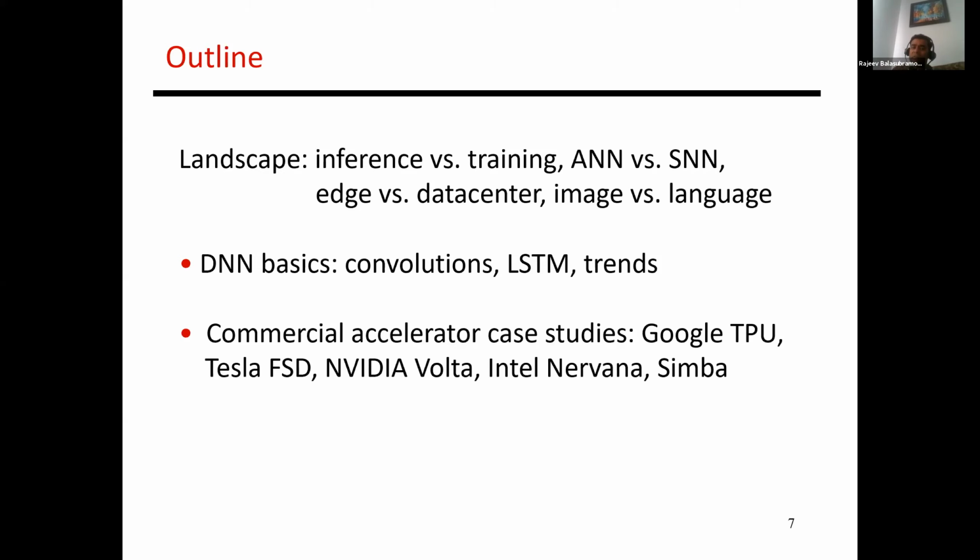The chips whose design I'm going to discuss could either be employed in a data center, where training usually happens, with much higher power budgets and cooling budgets. In those cases, you would design a much bigger chip that's perhaps focused on throughput. At the other end of the spectrum, you may have chips that go into edge devices like your phone, or sensors in the wild. Those devices have much lower power budgets, so you might want to design a chip that consumes less than a watt. So we can design for different markets and domains, but some of the principles I'm going to discuss in these 3 lectures will apply to both.